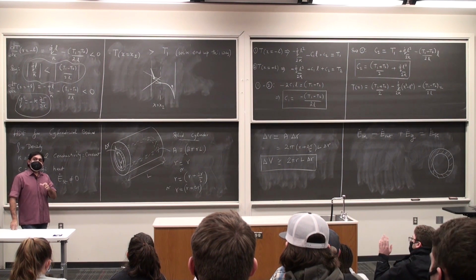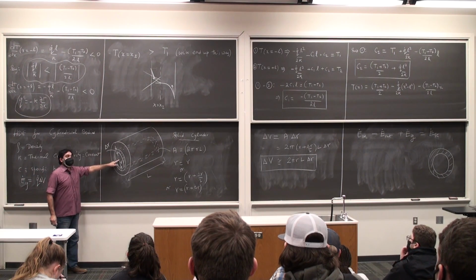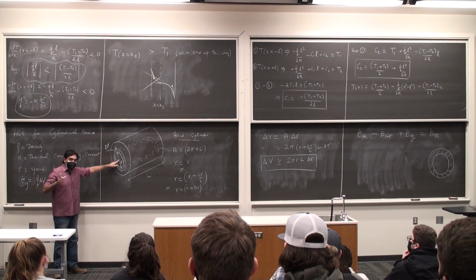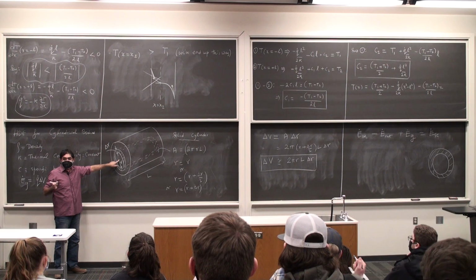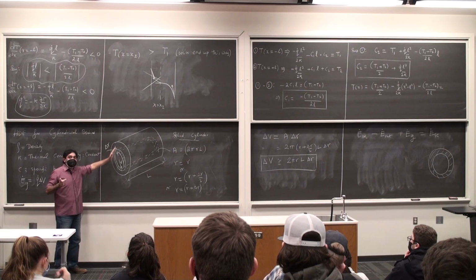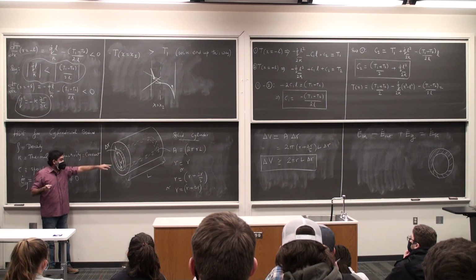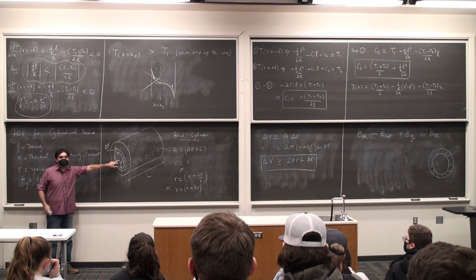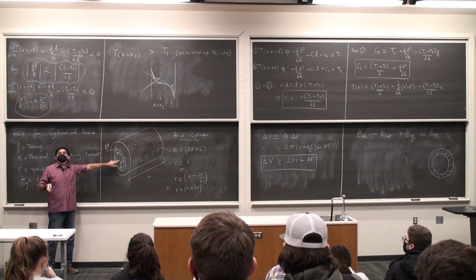We are saying something really, really critical about a boundary condition at the center of the solid cylindrical body. And I am saying that heat can travel in only one direction, either in or out. So in this case I am saying that heat is traveling radially outwards, which implies that no matter what you do, the conductive heat flux at the center point should be 0. Okay, that has to be the case. This is the symmetry boundary condition.